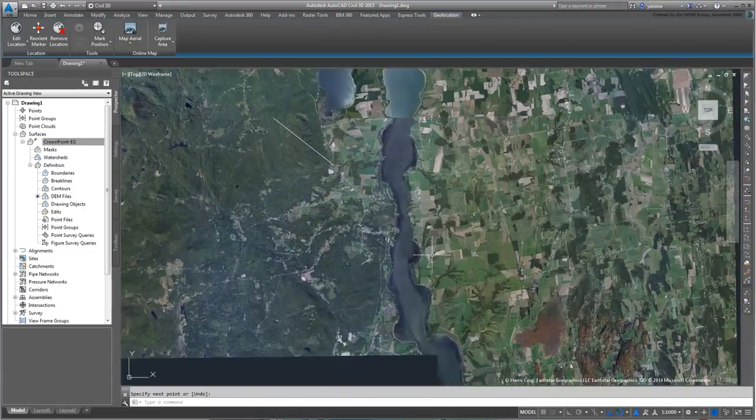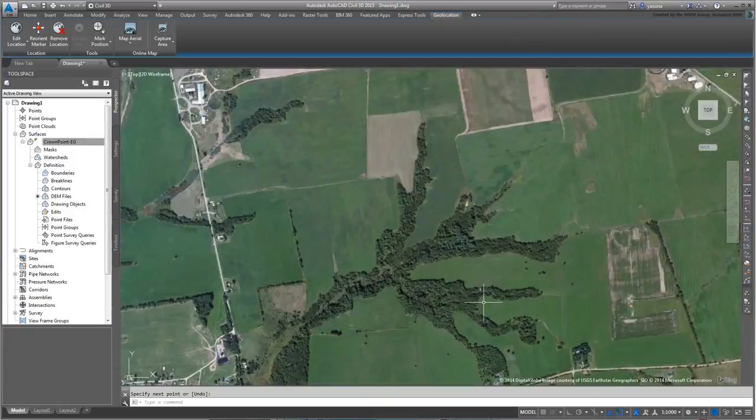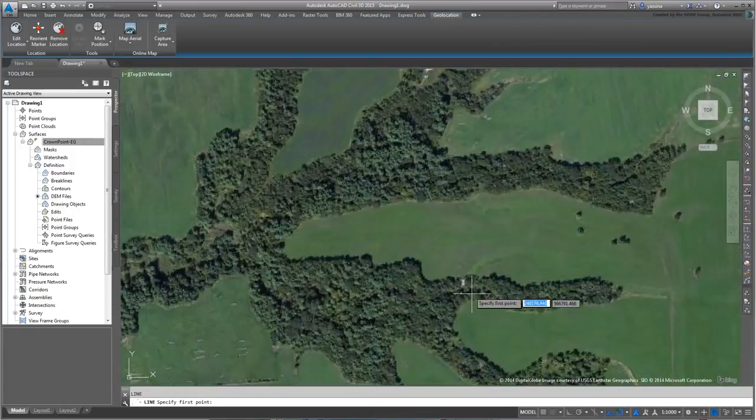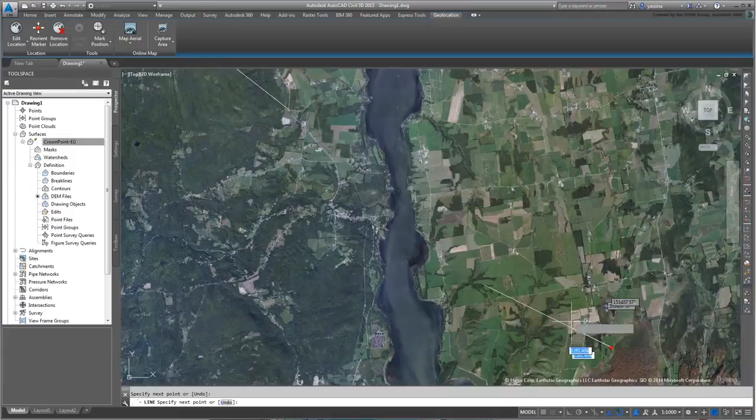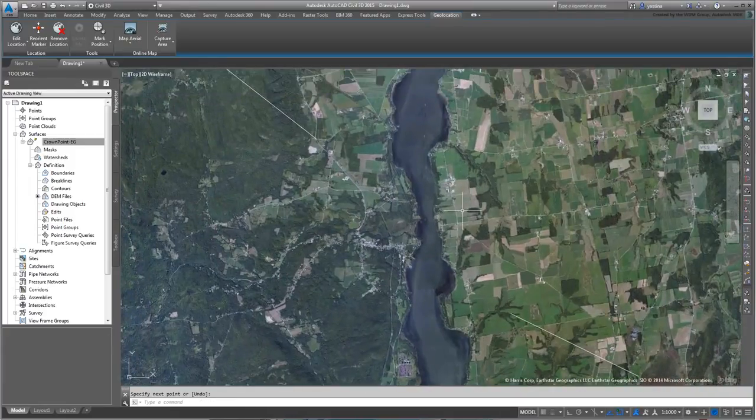Zoom back and create another temporary line, starting at the white speck among the trees, the same one you also used earlier. Now create a rectangle by snapping to those two reference points. If your object snaps are not active, use the F3 toggle. Delete the two lines when done.